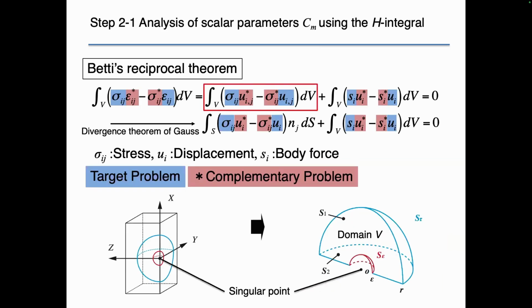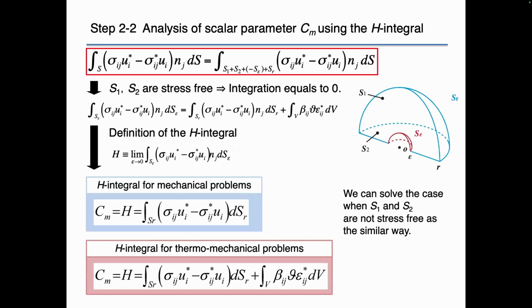After that, we obtain the scalar parameters Cm using another numerical analysis based on Betti's reciprocal theorem. This is Betti's reciprocal theorem, like this. And we modified these equations like this. We obtain the H integral.